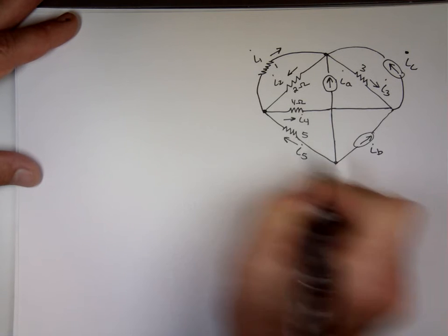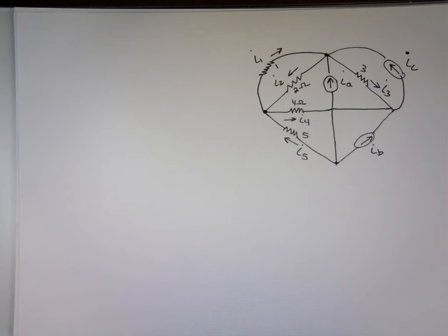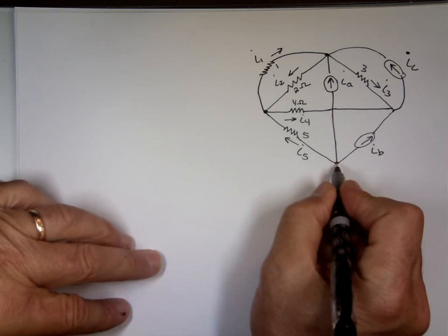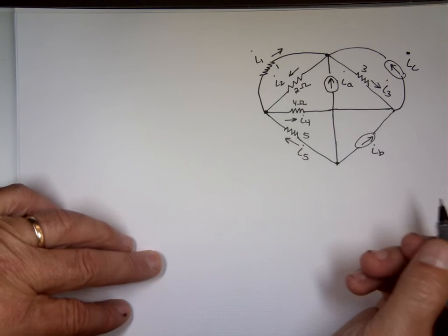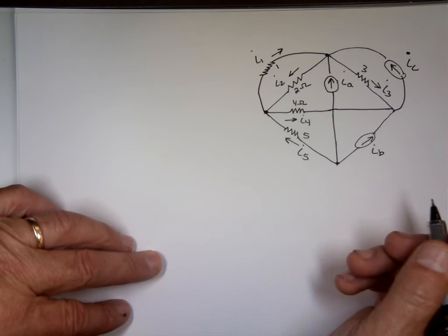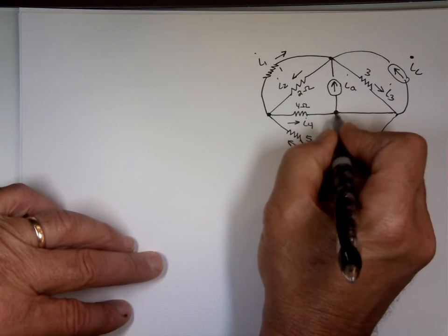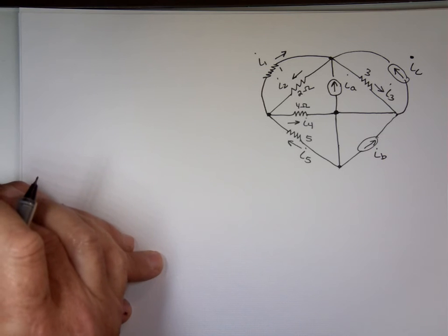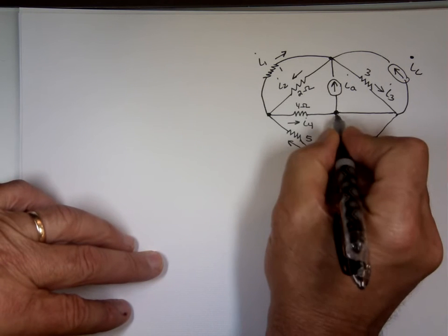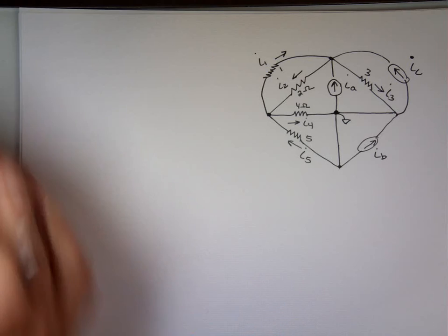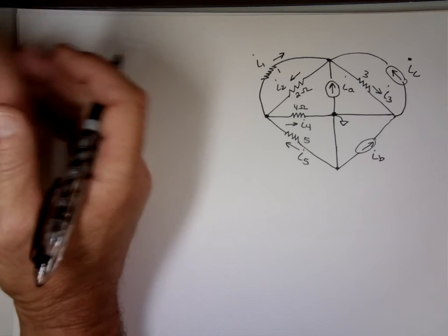Okay. So let's look at the nodes. Usually we need to have a ground in the circuit. So which one do you want as the ground? Want to make this your ground? It doesn't really matter. You can pick any node. That could be that one, could be this one, could be that one, the ground. So let's look at that node. That'll be a good ground here. There we go. That's ground. If you were building this in the lab, you've got to attach a ground to it.